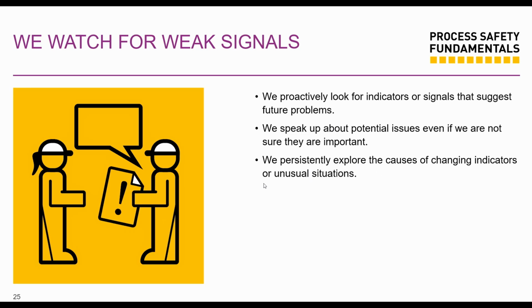Now, a simple example is what I said earlier. You notice a pump seal is leaking very small amounts of hydrocarbon during startup. Once you start up that pump, it leaks for like 5-10 minutes and then kind of seals off. We have those situations that happen. It seals up and the leak stops after 10 or 15 minutes of operating.